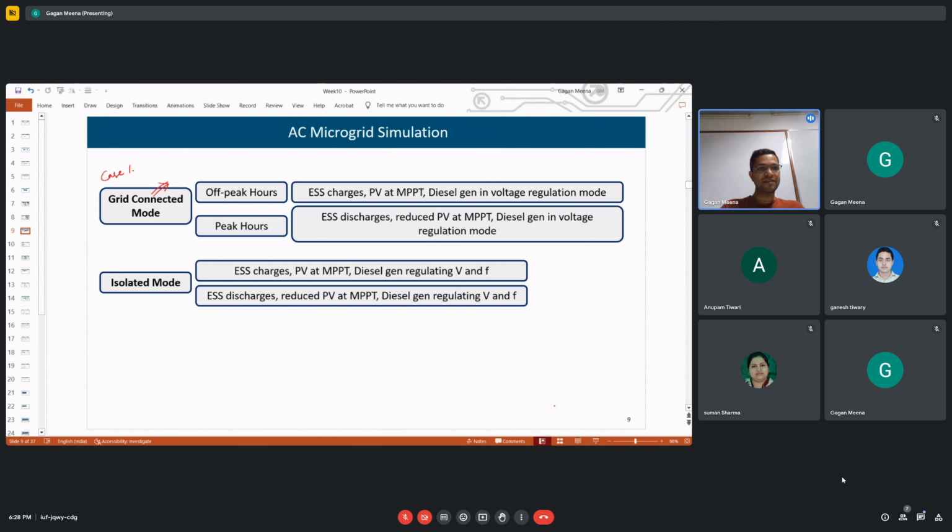So we connect an inductance, a shunt reactor there, to absorb the reactive power, and that brings down the voltage. So they are used because of their low cost, simplicity, and robust structure, and because of their reactive power compensation. For this purpose, they are used in transmission system, and even in distribution system, they are used for